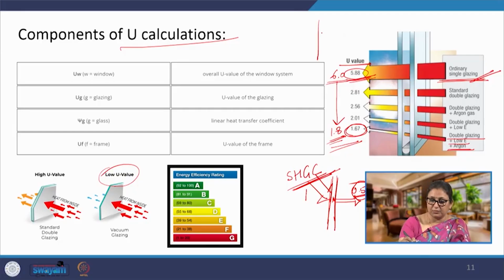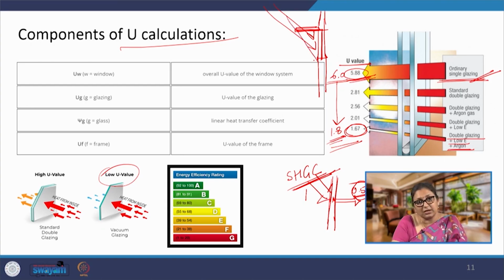But imagine a scenario where there is no direct radiation coming onto the window, and how can it be? Suppose I have a window on a wall, this is the window we are assuming. Now, there is direct solar radiation which is going to be falling onto this. What if I have a chhaja, an overhang which cuts the solar radiation significantly? There is no solar radiation that is incident. The SHGC remains the same, but the amount of heat that is transmitted inside is significantly reduced.